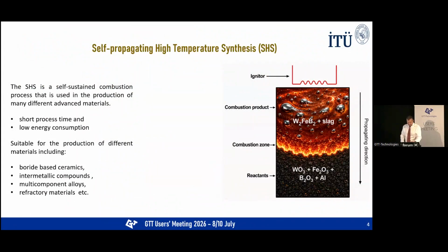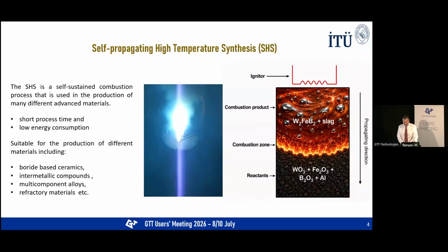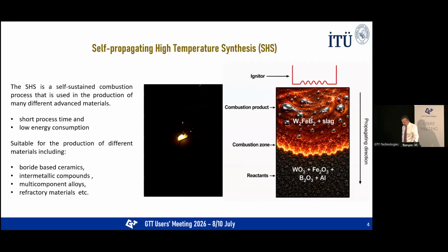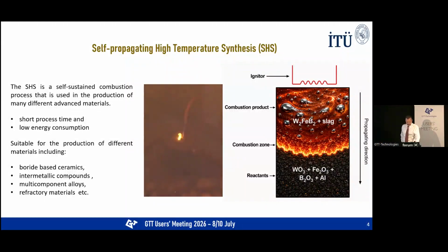Before discussing the results, I would like to briefly introduce the SHS process. As you see, it is a quite exothermic, combustion-based synthesis technique. Once the reaction is ignited, it becomes self-sustaining, and it is faster and more energy efficient compared to other furnace processing. On the right-hand side, the combustion front moves through the compacted powder and converts the oxide from top to down, and you get the desired alloy and slag.